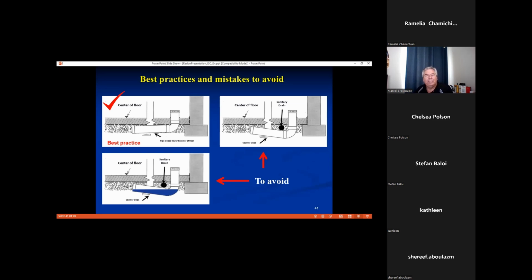The day may come where we may have to put a radon fan in to create that suction underneath the concrete floor, because radon is getting in and the levels in the home are high. Whenever we install a radon fan and pull the radon from underneath your concrete floor, we also get all the humidity that comes from the soil.